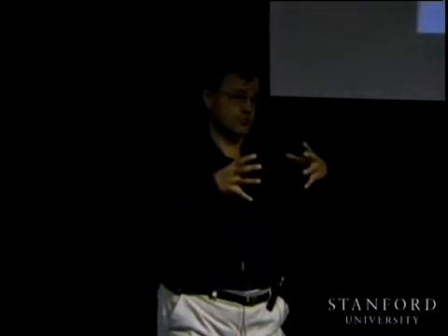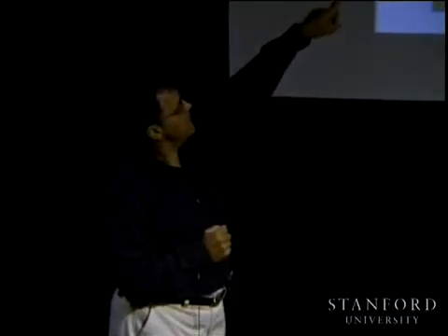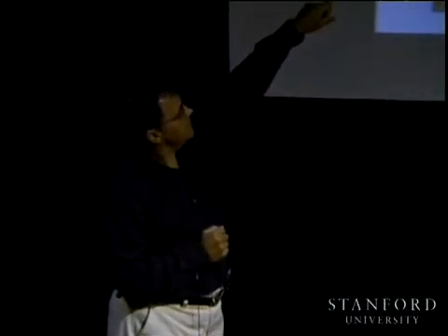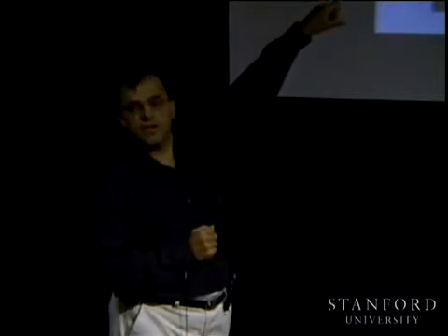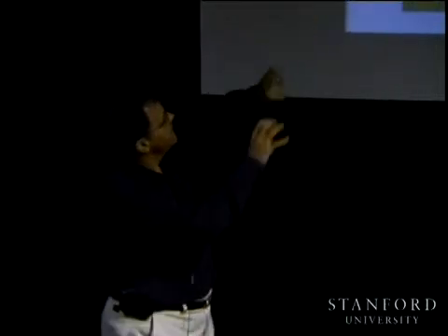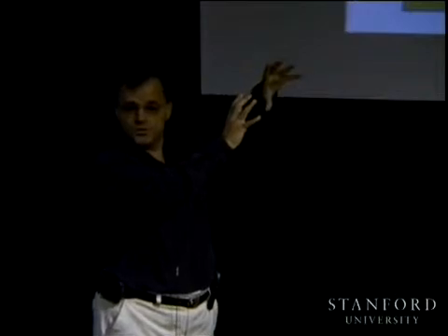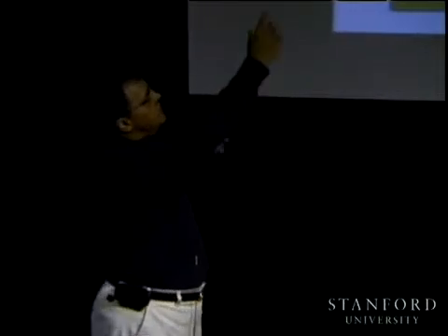Basically, we take the obstacles and we grow them by the size of the point robot, if you want. If you look at the red dot there, the idea is that if we plan a path for the red dot that doesn't collide with these grown obstacles, then we know for sure that the circle is not going to collide with the smaller target obstacles.